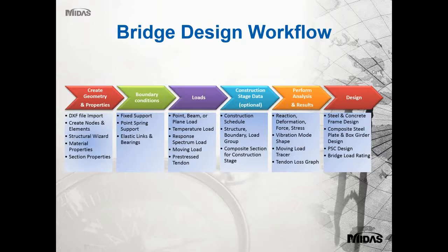The design workflow for any kind of bridge that we follow in Midas involves creating the geometry first of all and assigning its properties. Geometry can be either created within the software or brought in from AutoCAD files, basically the DXF file format.